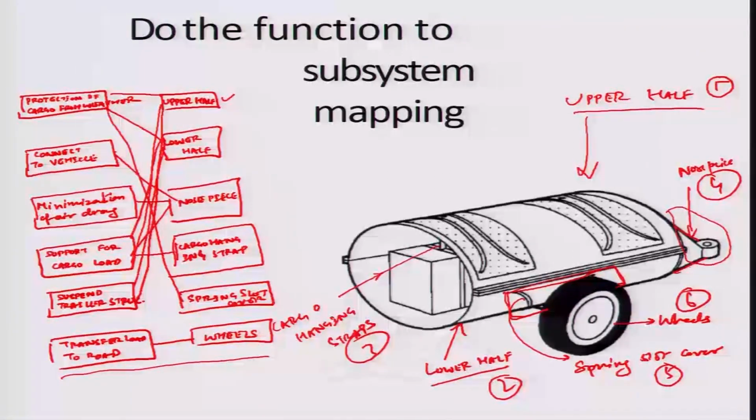So, if I really were to look at such an item, it is modular in a way that you have individual subsystems performing some of the other functions, but just because there are multiple functions being performed by a single component, you could say that the modularity is a little more complex. For example, in this case the fairing and the hitch have been connected together and are now one module instead of the earlier two modules which were put in place, okay. So, in a way such kind of information goes towards what you call complex modularity.